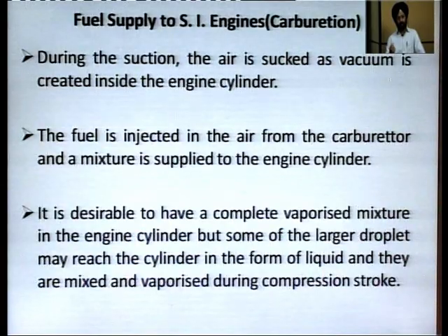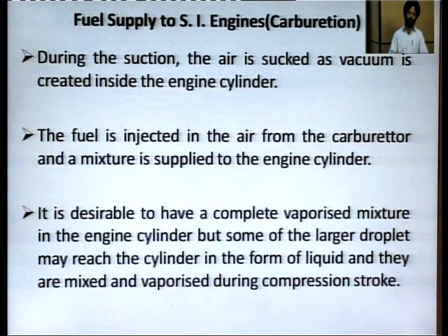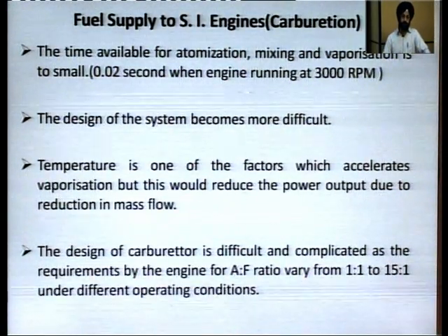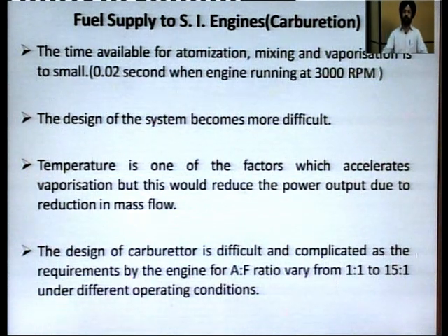At the end of the suction stroke, when the piston is at bottom dead center, the compression stroke will start. It will agitate the air and fuel mixture, and those droplets, if any, will be further broken up. But the time available for atomization, mixing and vaporization is very small: 0.02 seconds when an engine is running at 3000 rpm.